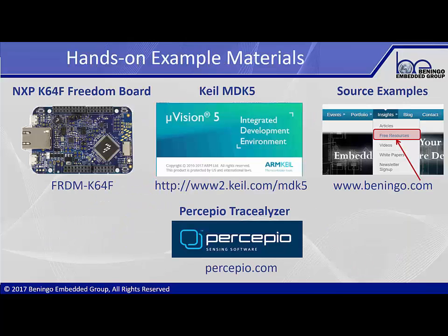Now, just like with most of my webinars, I like to take a hands-on approach. So what I did was I got a development kit, an NXP K64 Freedom board. I'm going to be using the Keil MDK 5, the latest version, which is 5.24. I have a simple example that I put together that has a couple of semaphores, a few threads that interact and blink some LEDs.